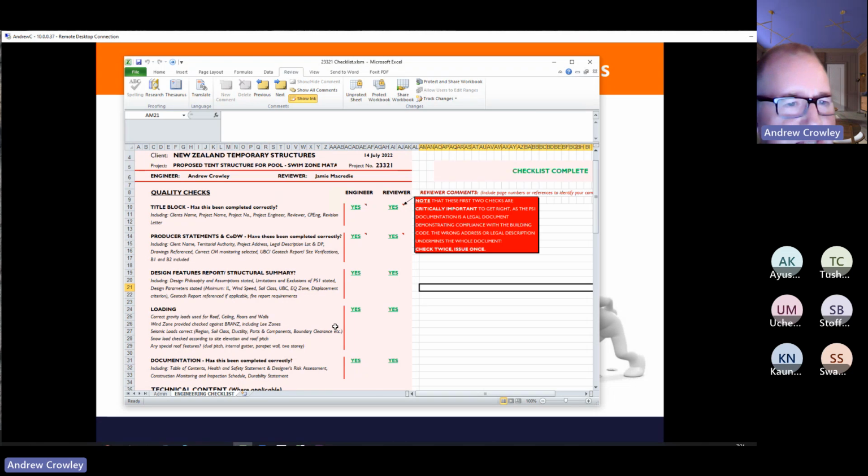So it's some fairly basic stuff. Have you got the title right? Have you got the job number right? Have you got the correct revision and titles and so on? And if you get the PS1 wrong, the councils can throw them back. So if you've got the wrong address or the wrong lot number, that can be sent back, which causes delay